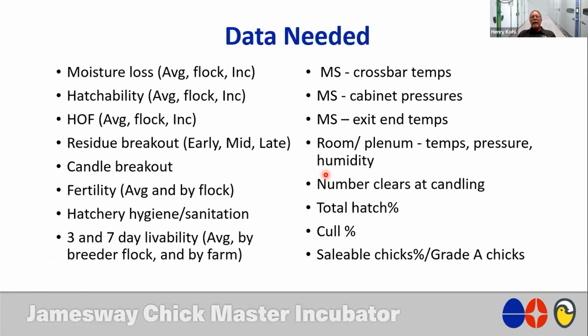It doesn't matter what incubator you're using or hatchery you're using. Your rooms, your plenums, your temperatures, your pressures, and your humidities need to be correct according to the manufacturer's specs of that machine. If not, you're going to have issues with that equipment not operating the way it ought to be operating. So, just a few more things there.